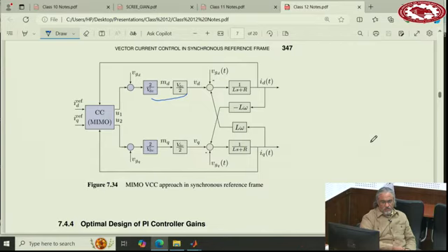See, when you have harmonics, for instance, in the grid voltage, and you want to prevent them from going to the grid current, right? So if they are in the grid voltage, and we discussed that they will, through that transfer function that we showed, go to the current anyway, so you have to stop them. And then we put resonant controllers at that particular harmonic, 5 for instance, or harmonic 7. So if you really want to remove one harmonic completely, you need to put a resonant controller for it.